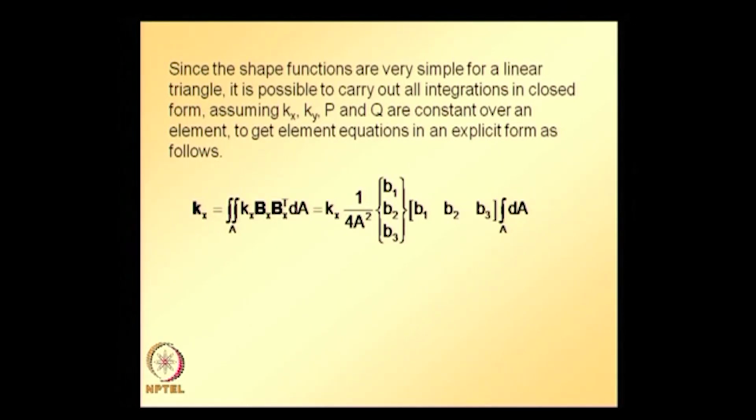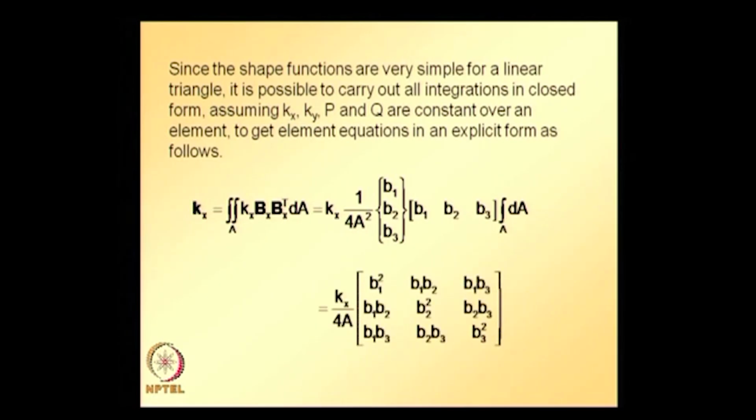Substituting bx and bx transpose, this integral can be simplified in the form given in the slide, and the integral over dA is going to be A. Expressing kx in a closed form like this is possible only if the coefficient kx is constant. If it is not constant, the integrand becomes complicated.